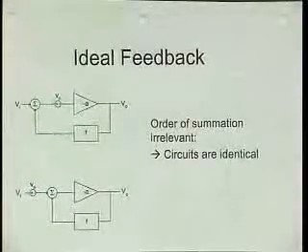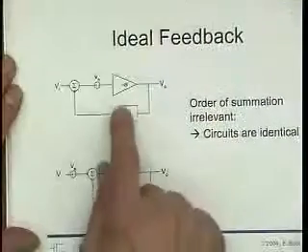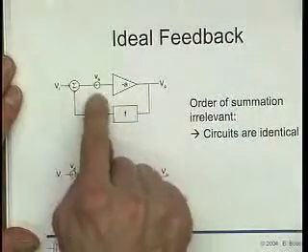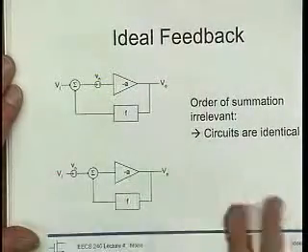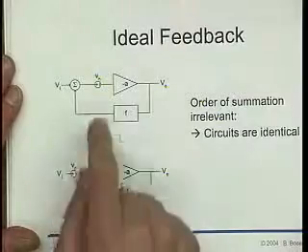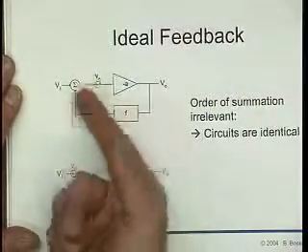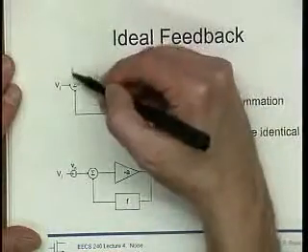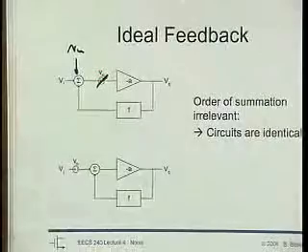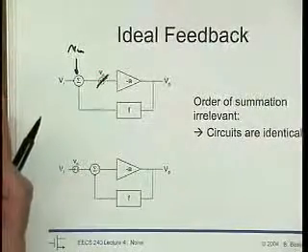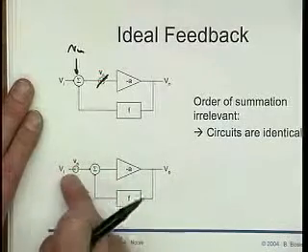Okay, so I mentioned something about ideal feedback. So here is what I mean by ideal feedback. We have an amplifier. We've calculated its input-referred noise, and we apply feedback around it like this, right? Sort of like a MATLAB simulator kind of approach. Well, the feedback really just gets added to the input of the amplifier, or we could actually represent this as just get rid of this thing and just add the noise to zero. It would be the same thing. And then it's a simple step to just move the feedback noise out here.